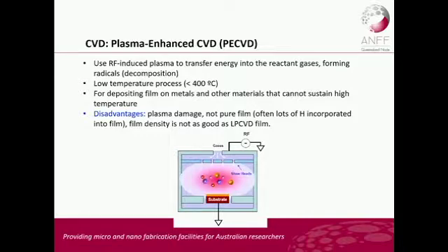So the next is another CVD process, called plasma-enhanced CVD. In this CVD, we use plasma to transfer the energy and to activate the reactive gases. Compared with the LPCVD process, this is a low temperature process. Usually the temperature is less than 400 degrees.